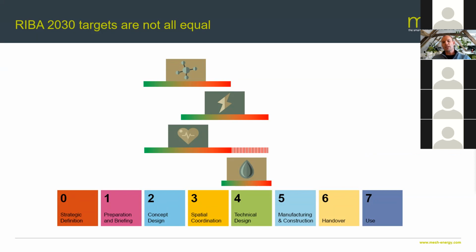Depending on what you're designing, choosing principles of construction affects, say, embodied carbon. And the amount of glazing, the aspect and orientation of the building, the various facades that you're using, and the look and massing of the building also affect overheating and daylighting and all those kinds of things which come into health and well-being.